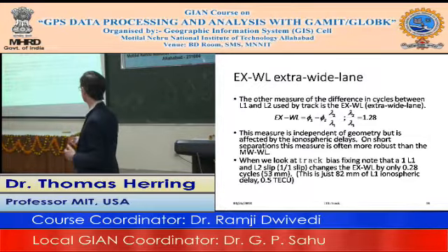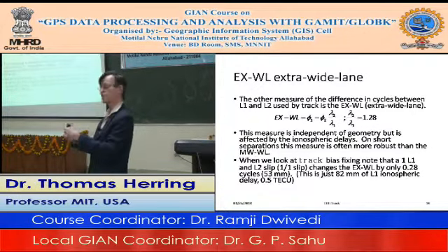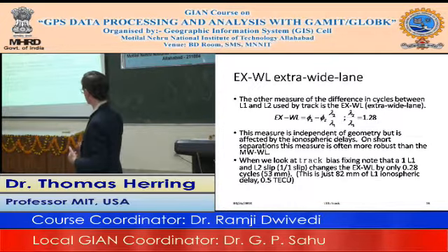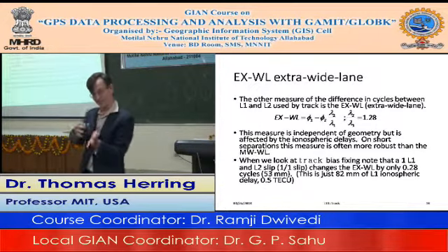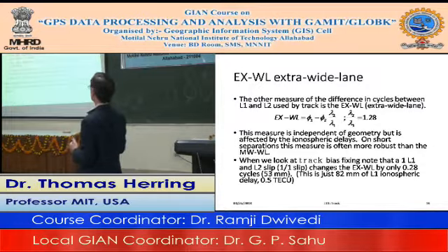So with this 53 millimeters, you get an ionospheric correction of about 82 millimeters from a half-TEC unit of ionospheric delay. And so if there's a differential half TEC unit, then this is going to start getting confusing and difficult to resolve. That's when you rely on the LC combination to be able to resolve it as you go across. But on short baselines, that works really well.